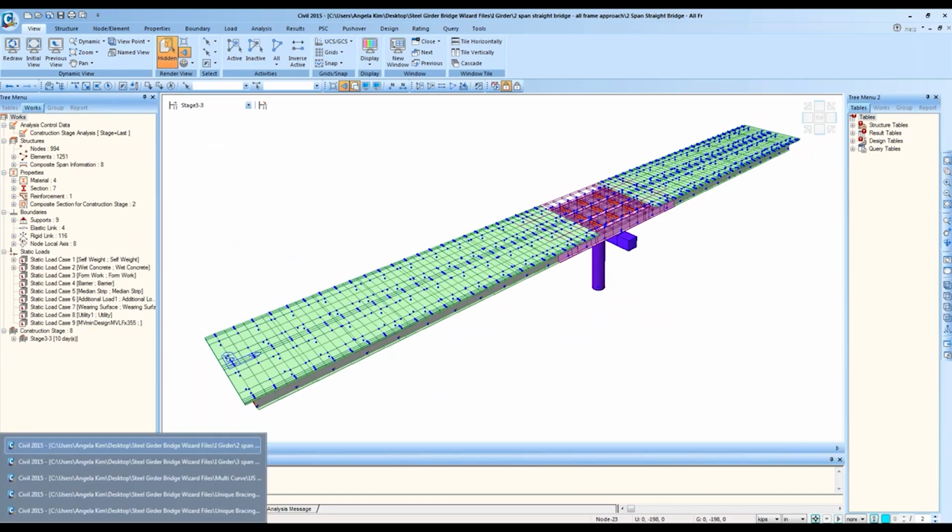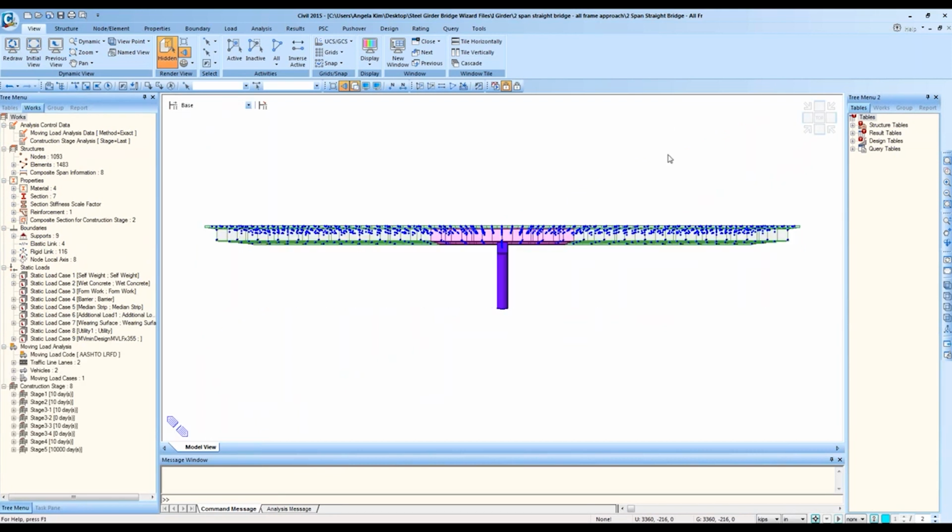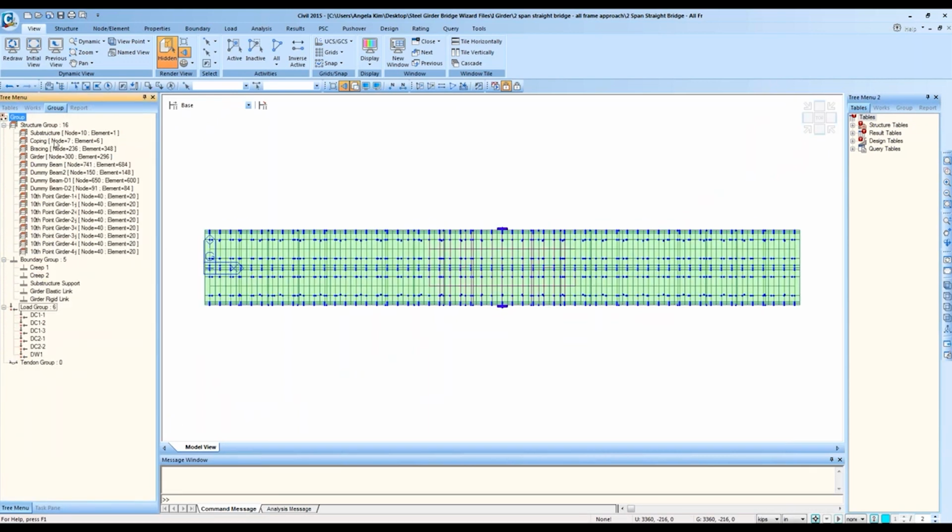And here I actually forgot to mention, if you want to reflect girder installation sequence, right now I have a girder group, and all the girder elements are included in the girder group. But if you want to sequence your girder installation, let's say you want to install first the inner girders and then the exterior girders, then you can create girder 1 and girder 2 and activate them in different stages. More about the construction stage we'll be covering more specifically in another type of session.